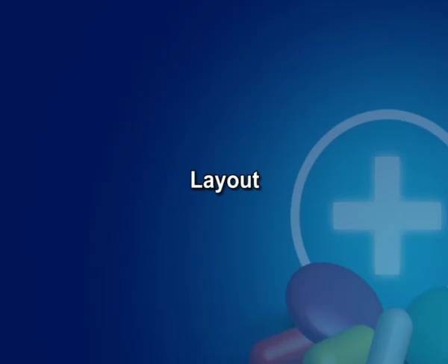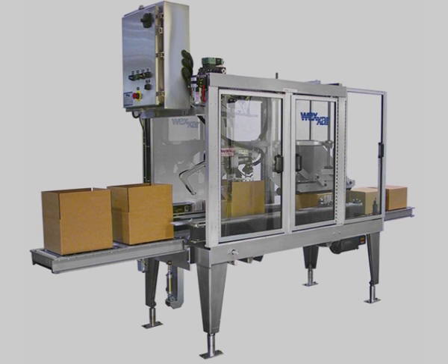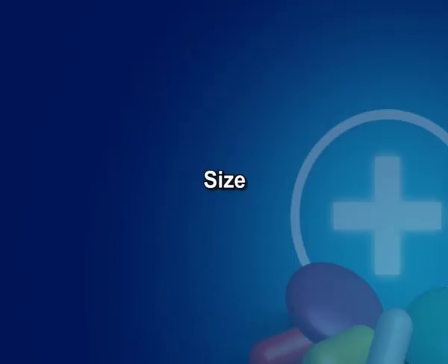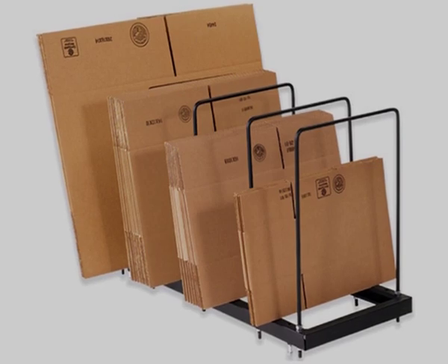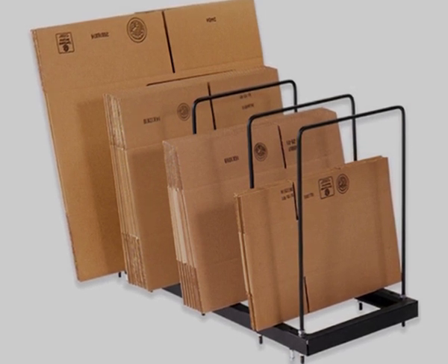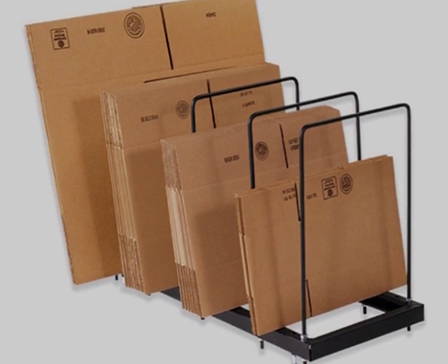Number 3. Layout. It is usual to have the top opening flap opening away from the opener with the glue flap around the back of the carton placed so that it interferes as little as possible with the overprinting operation. Number 4. Size. This has been mentioned above. Only make the carton big enough to contain the contents and allow enough clearance for machine operation.